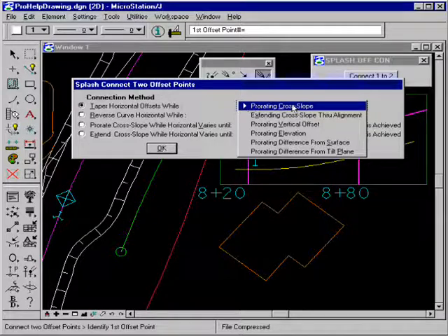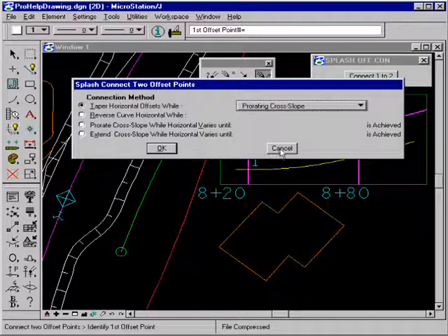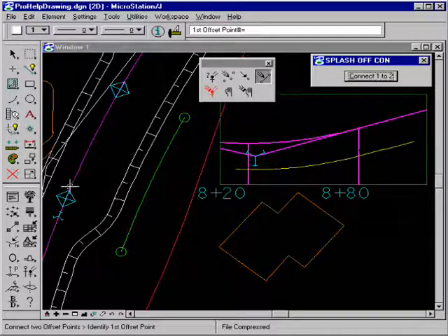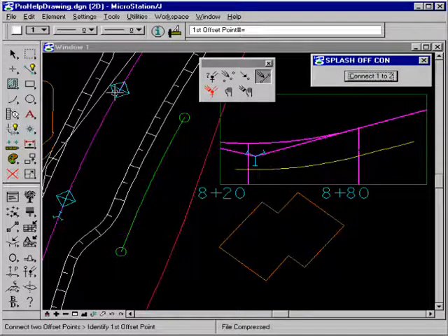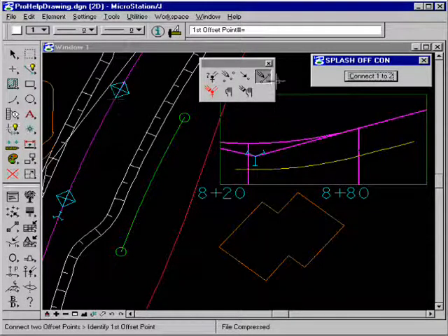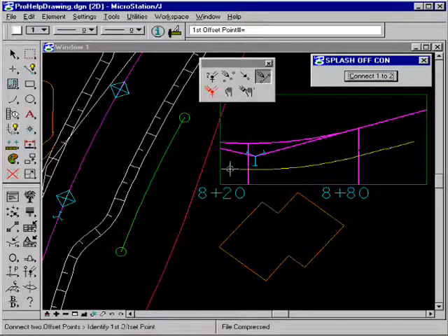Now, at the moment, we're prorating the cross slope. So we can see the effect of whatever the slope is out here. There's one slope it takes to come over 35 feet and go however deep it is in the ground. That'll be some slope. Over here, we've come 35 feet and gone 3 feet in the ground, and that's going to create some slope based on what the elevation of the parent happens to be at those points. So we see the effect of prorating a cross slope on the profile of this alignment.